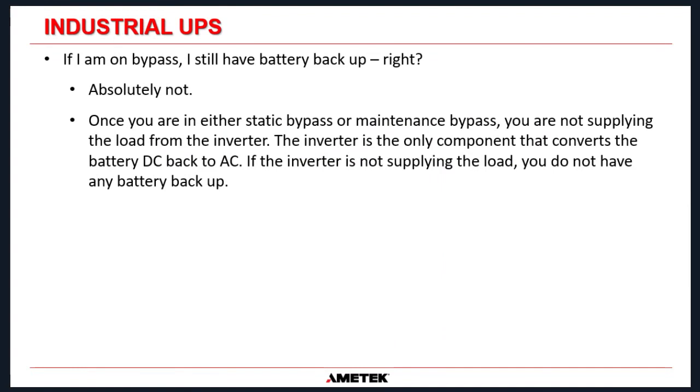The next question, if I am on bypass, I still have battery backup. Isn't that correct? This is probably one of the most common misconceptions out there. You absolutely have no battery backup whatsoever if you are on bypass supply. Whether you are in static bypass or maintenance bypass, it doesn't matter which one it is, you are not supplying the load from the inverter.